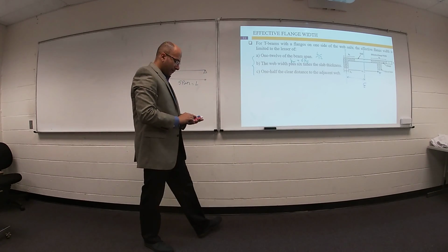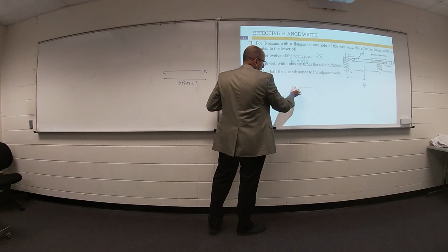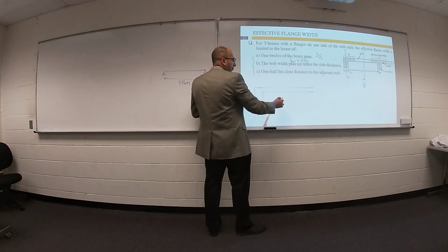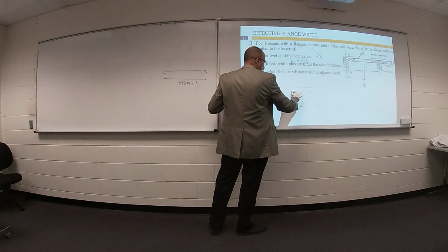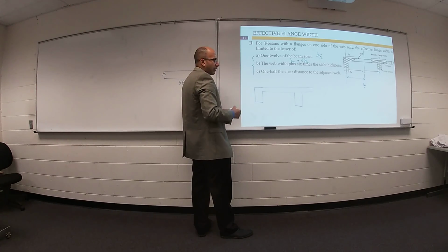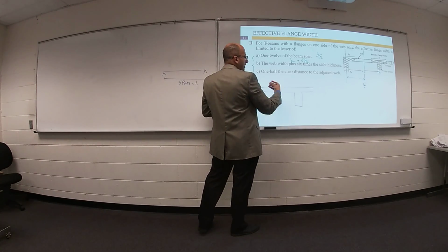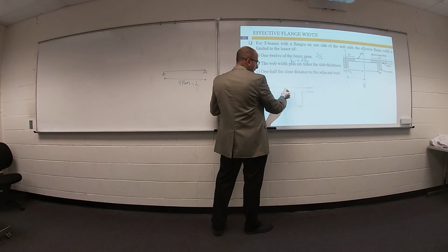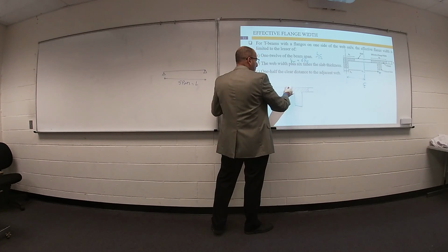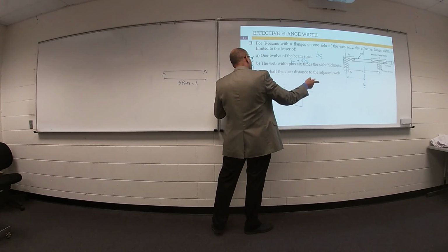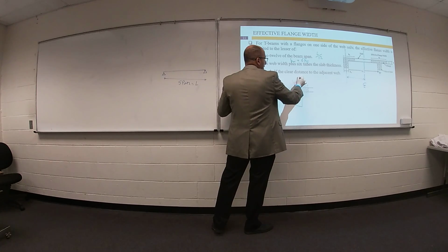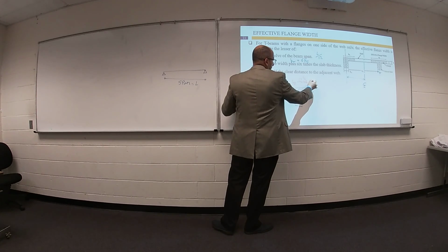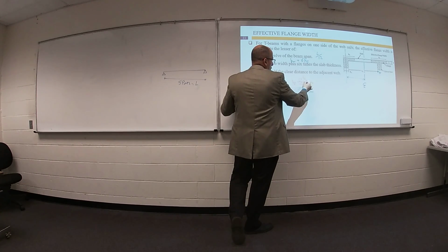So we have two situations. Here is your slab thickness; sometimes your beam is at the edge, sometimes your beam is an intermediate beam. We are talking about how much width of your slab is working with your beam. If your beam is intermediate, we have a little bit of your slab with effective width B flange, maybe quarter span, maybe 16 H plus B web, maybe center line to center line.